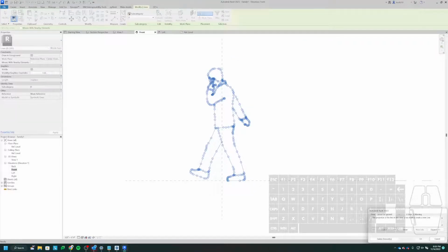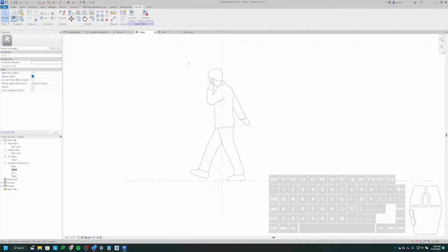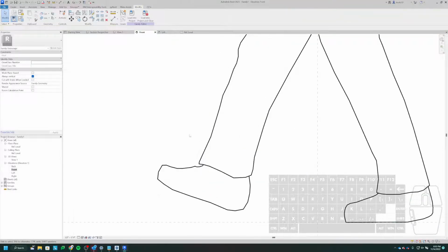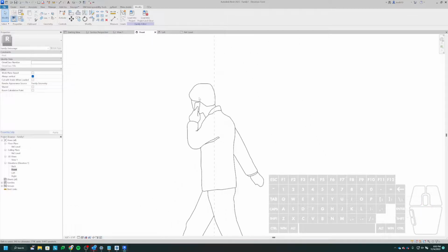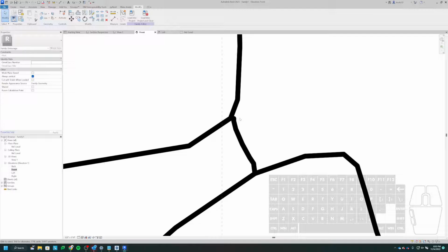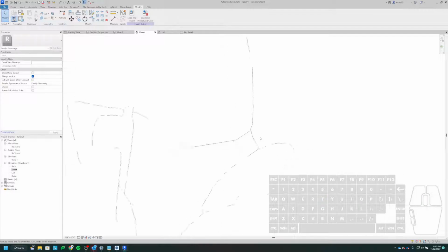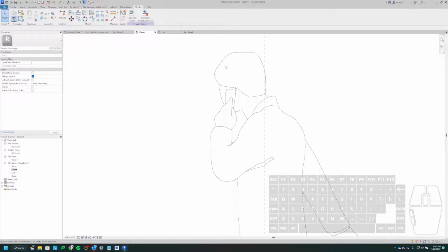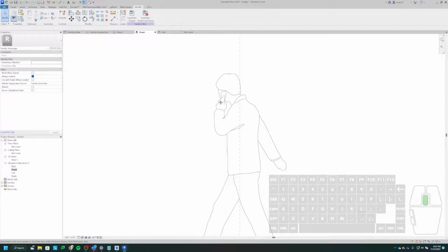And depending on how complex this drawing is, it might take a while. And sometimes it might give you some errors, but usually it'll just tell you that it converted all the lines over. And any errors you get, just hit delete element. It's going to delete those. So there's just a couple little lines somewhere where it didn't like them, and it didn't bring them over exactly. So if I turn off my thick lines, I may be able to see this a little bit better.